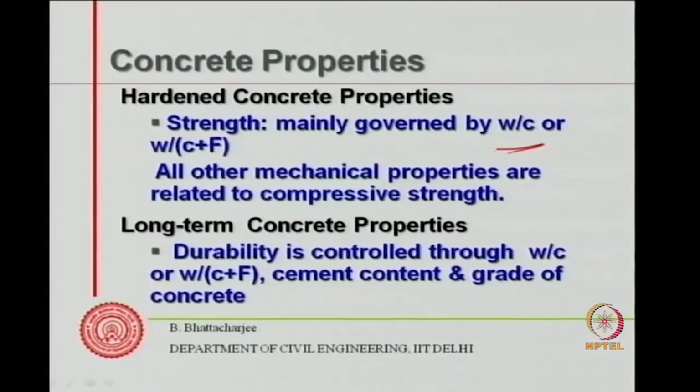Why does water cement ratio govern this? Because water cement ratio controls the porosity and pore sizes of cement paste, as we have seen. Even in concrete, the same thing happens. We have seen in the microstructure development of cement paste that it is the water to cement ratio which governs the capillary porosity.